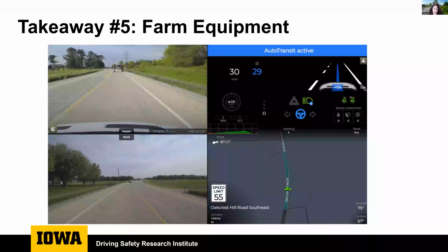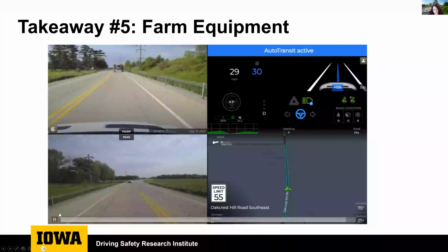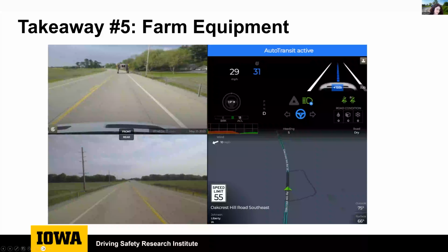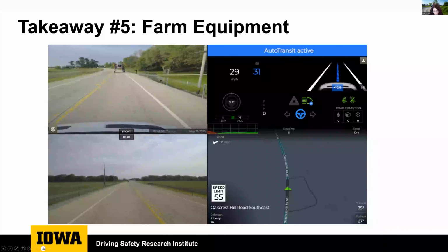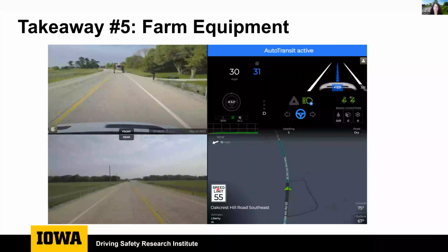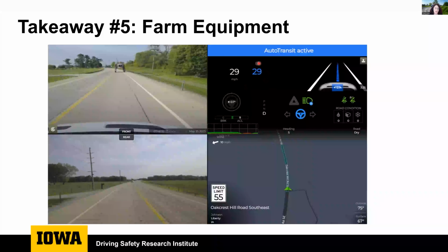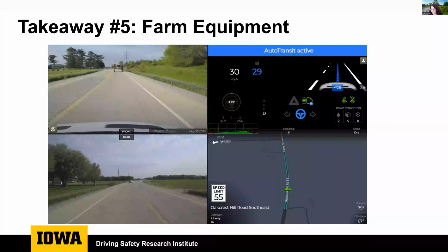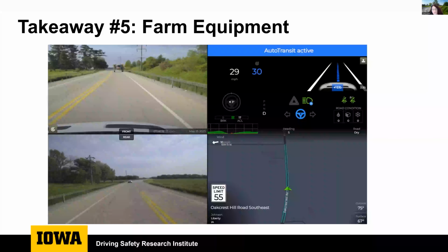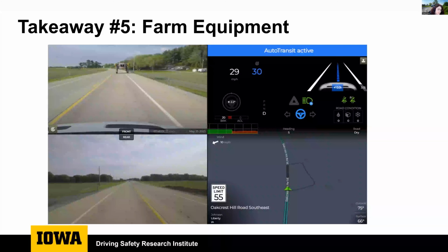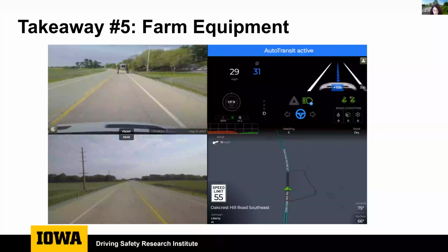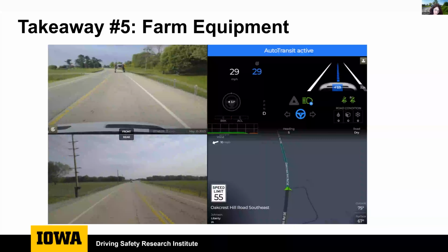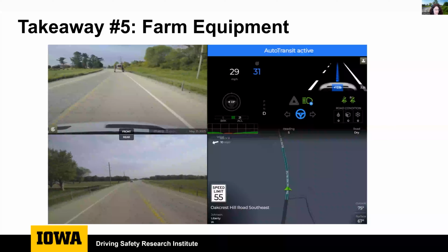Now, the current state of the automation on our particular vehicle doesn't allow it to leave our lane of travel to be able to pass. So we will sit behind this vehicle until it is no longer in front of us. Now, that necessarily isn't a huge deal for us since we're just traveling along, but it could be a concern for the traffic around us. People can get irritated. A vehicle queue can extend for many cars. People might decide they need to pass from 5 or 6 cars back. Now, this is just one encounter, and we were able to stay in automation, but this isn't always the case.